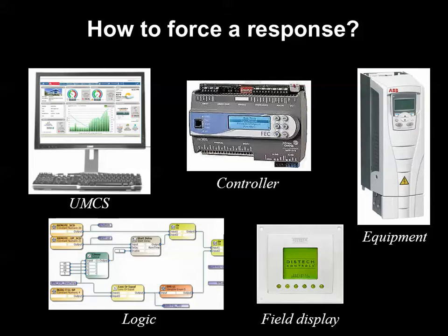Use your knowledge of HVAC fundamentals to think about what should and could happen when you intervene in system operations. If you're testing VAV airside systems for something like zone scheduling or duct static pressure set point reset opportunities, make sure discharge pressure sensors are installed and working. If you're doing a pump test, consider what deadhead pressure will be and how your pump seals may hold up to that. And if you're opening up access panels in an AHU while it's running, think about what filters and coils you may now be circumventing and whether that's okay given your space function.